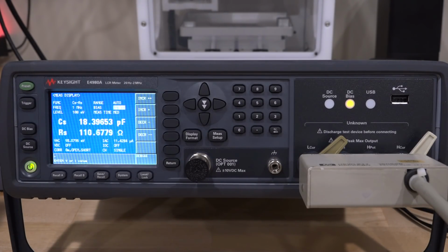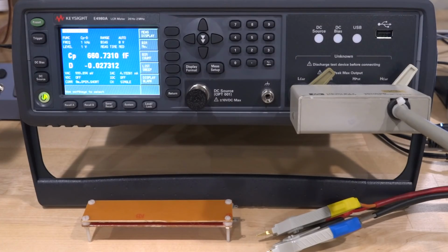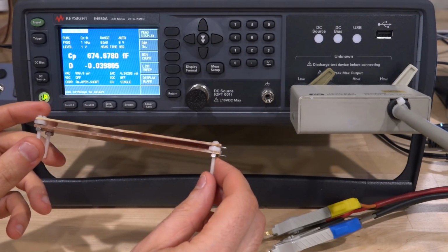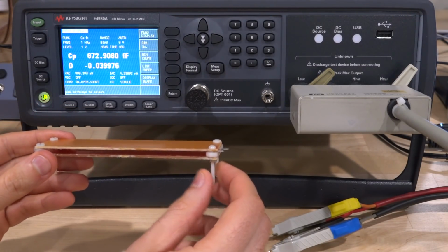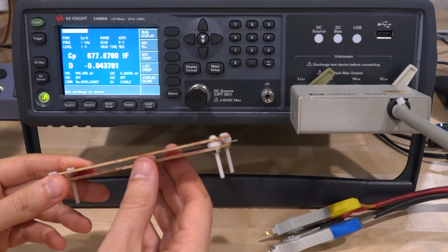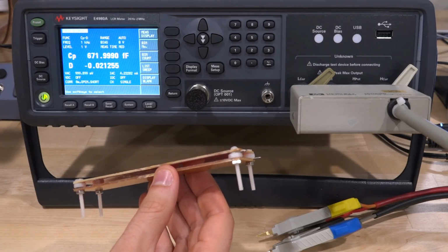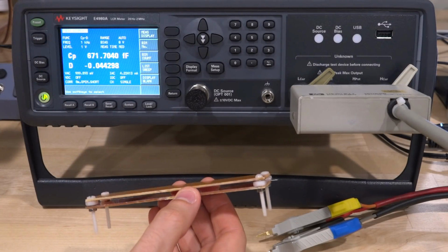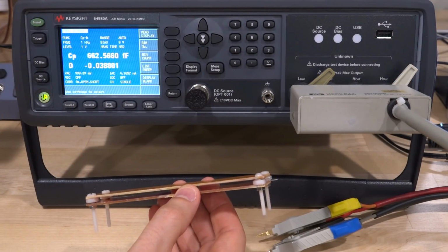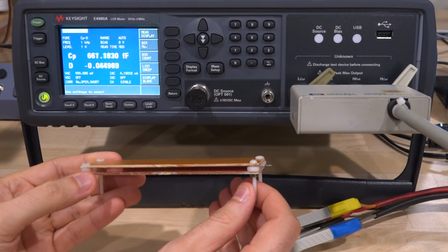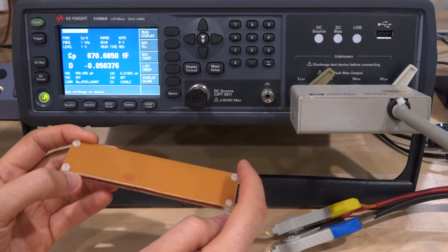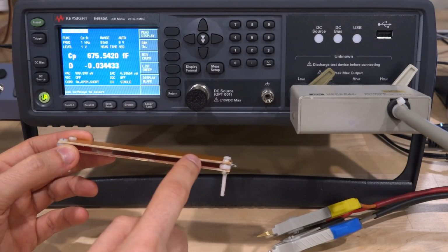Now we talked a lot about this, but I wanted to show you what I built about 20 years ago when I was playing around with capacitors for the first time. So here's my capacitor. It's really basic. It's nothing more than two parallel plates and some air gap in between it. So our dielectric here is air. It's made of a PCB with copper on one side, like this one. I just cut it into this shape, and I put a layer of tape on top of the copper side to insulate it as much as possible, and the screws are of course plastic so that they don't touch each other.